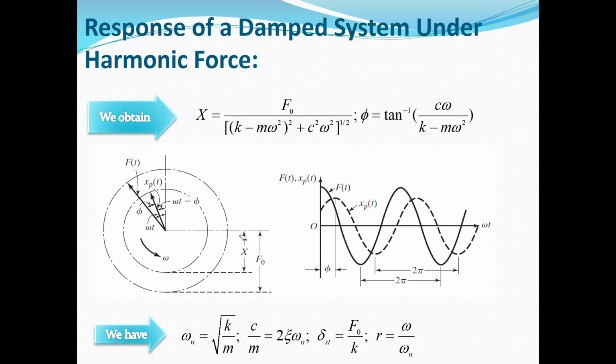Okay, so this is the response, and to substitute into this equation, you can also use the data from the previous section. You know that the natural frequency omega n is the square root of k divided by m, where k, in fact, is not the stiffness. This is the equivalent stiffness, I mean the coefficient of x in your equation, and m is the equivalent mass.